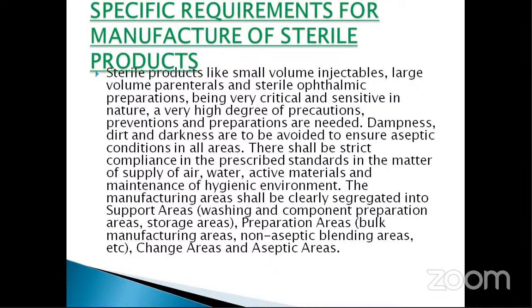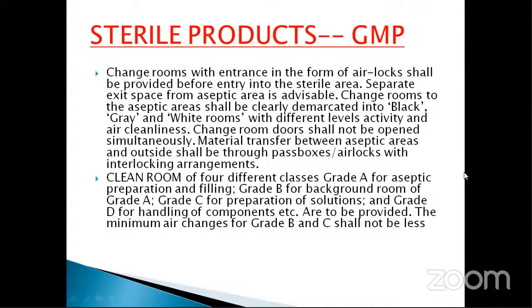Now, for the aseptic areas, whenever you are entering the aseptic area, the change room is a totally different kind of change room than for your oral liquid preparation or tablet and capsule preparations. There will always be 3 rooms: one is black room, one is gray room, and another is white room. First, you will enter the black room. Black room means the air quality maintained there is not so high a class. It may be a C grade room.